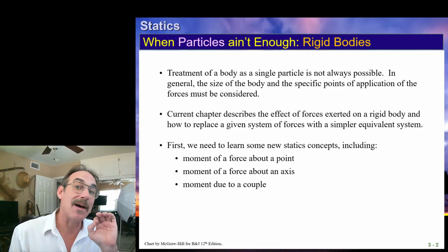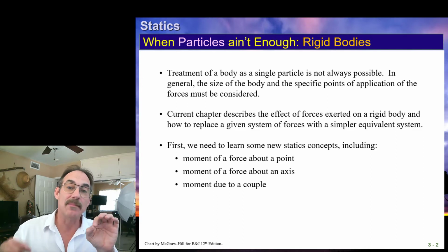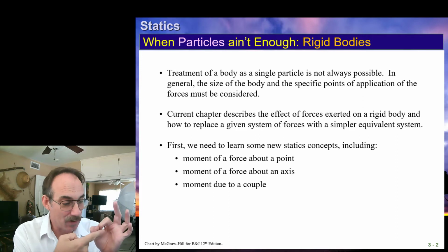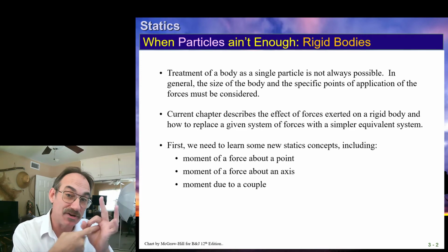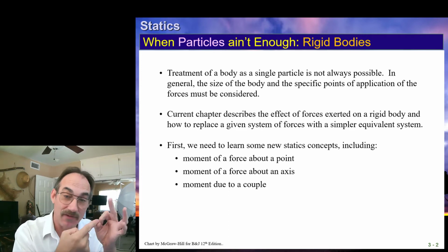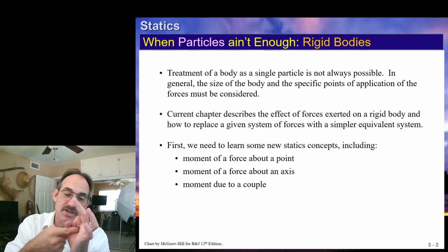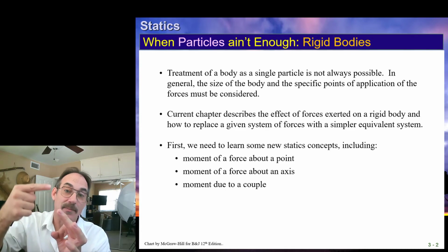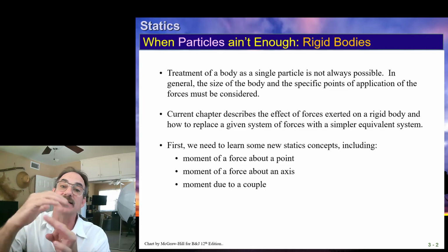Now, this is where we find out about moments. We've been learning about forces, and we're going to find out when a force acts through a point, then all we need to do is understand the translational effects of that force. But when that force is applied at some distance from the point, if it's not going through the point, but is applied at some distance, that perpendicular distance causes a moment.